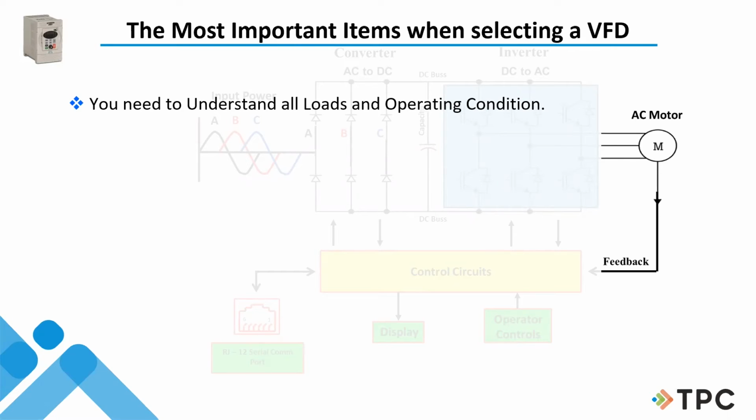If you're going to put it on something where you're metering something into a process, you better know how fast that drive's turning, because every turn is so many pounds or whatever of material going into the process. And I need to know what that is to make sure that my process comes out the way I want it to. So the very first thing I have to know is about my load. I have to know all the conditions that are happening out there. Talk to the operators, the best friend you'll ever have.